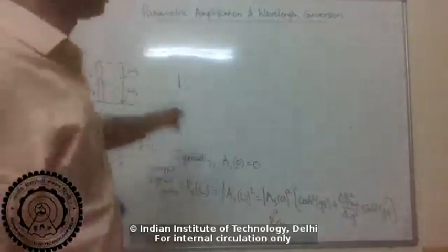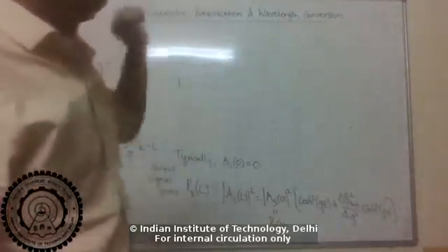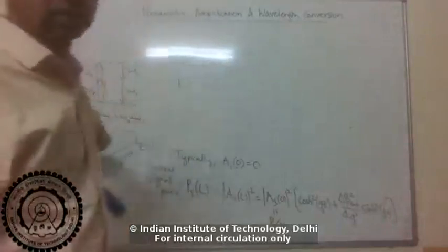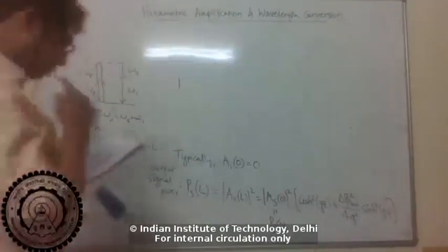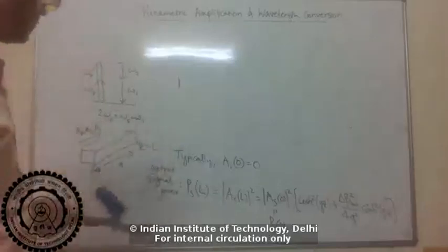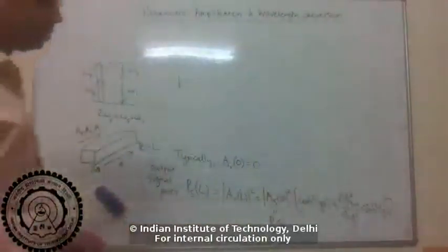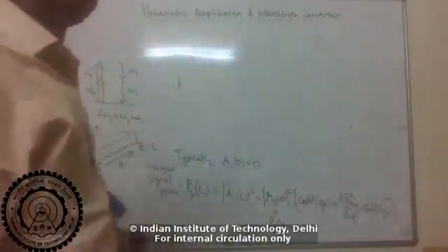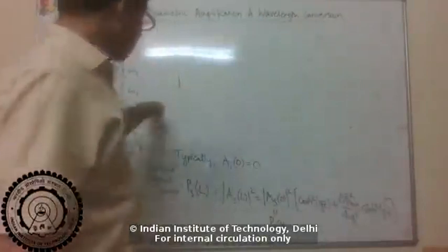If you want to do amplification, like build an optical amplifier which is efficient, or do wavelength conversion, then typically the co-propagating case is much more efficient than counter-propagating pumps. The main reason for that is phase matching. We saw that this delta beta total has to be close to zero for the process to be efficient, for this G to have a large real value. That's easier to do when they're all co-propagating.